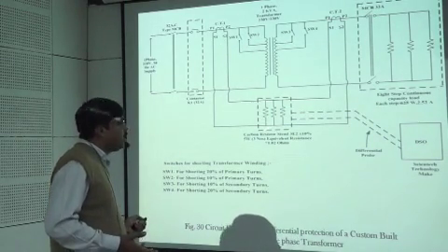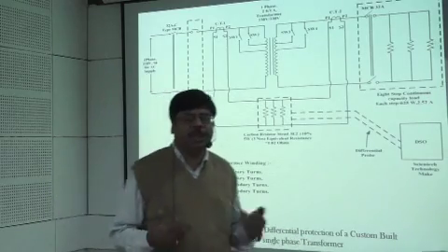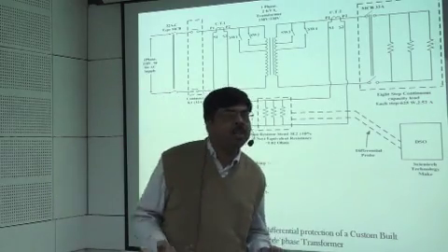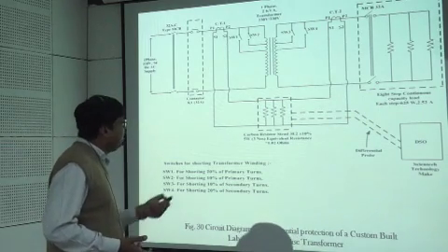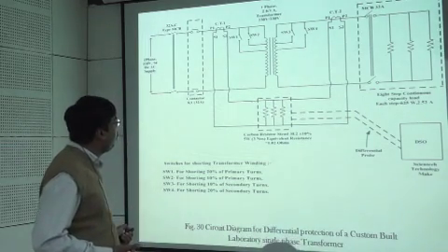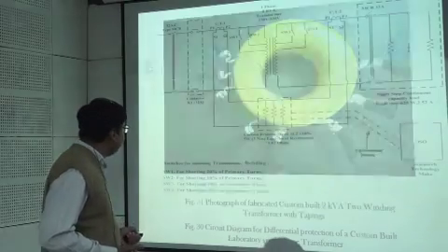Here I have used three resistors, each of value 3 ohm, 5 watt each, in parallel, so that the effective resistance is 1 ohm, and this is a load. Then we can observe the waveform of the differential on this DSO.